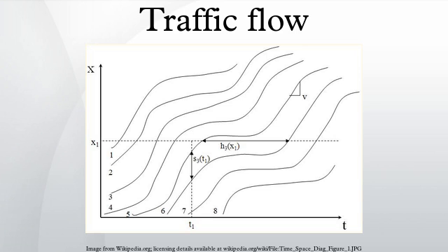Even if there were no stochastic processes in vehicular traffic, the states F and S do exist at the same flow rate. However, classical stochastic approaches to traffic control do not assume a possibility of an F→S phase transition in metastable free flow. For this reason, these stochastic approaches cannot resolve the problem of the inconsistency of classical theories with the set of empirical features of real traffic breakdown.